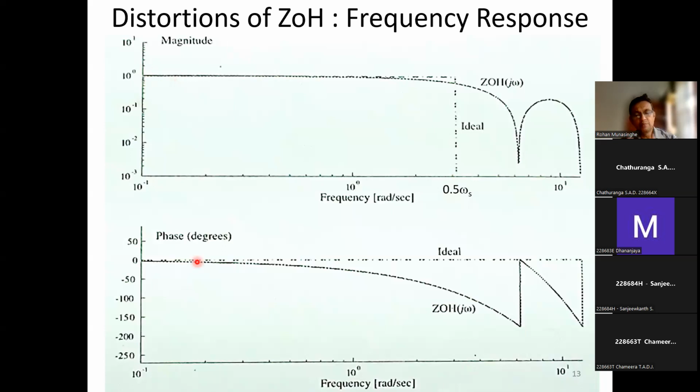So this very simple design criterion makes your life a lot easier without going through rigorous mathematical derivation. Simply set your sampling frequencies sufficiently high so that none of these anomalies that you see on the Bode plot of the zero order hold will have a chance to deteriorate your signals.